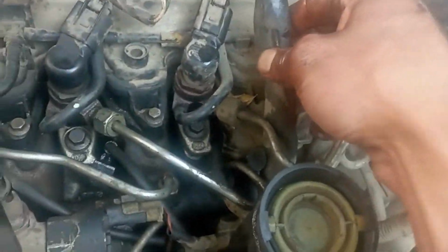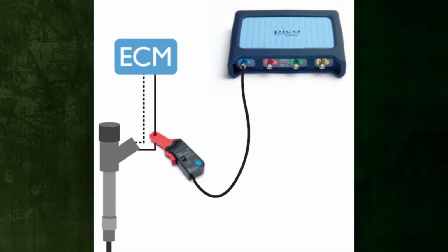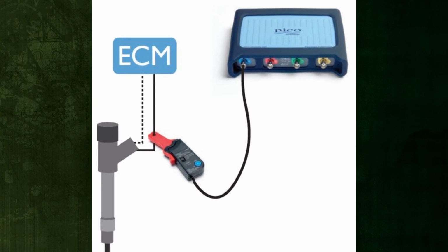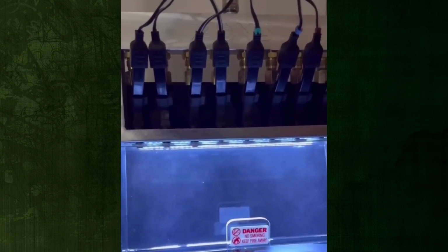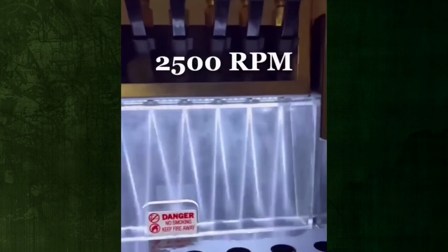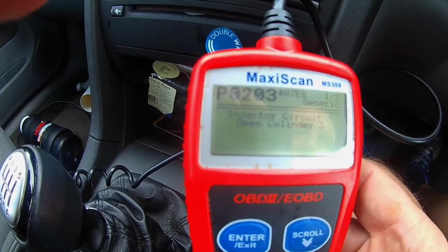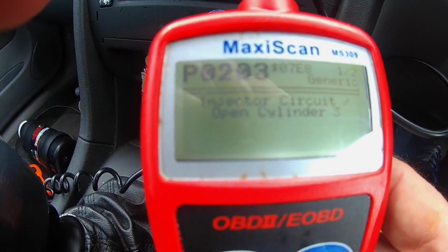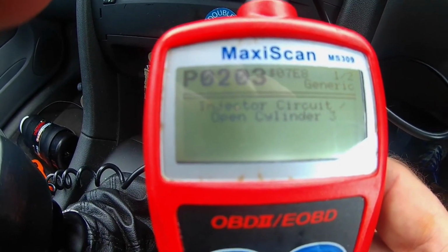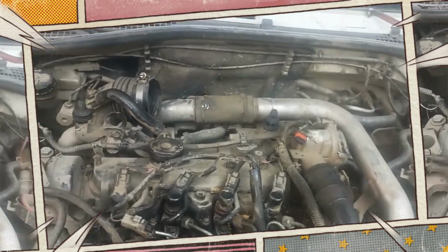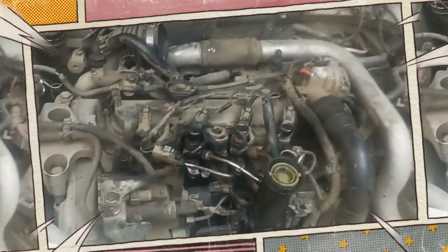To fully comprehend this principle, one must first comprehend the fundamentals of fuel injection operation. The ECM or PCM of a car powers individual solenoids, which operate each fuel injector in an engine. The ECM continuously checks each individual fuel injector circuit for measured anomalies in resistance and voltage. Diagnostic fault code P0203 indicates that during a commanded injection event, the engine's number 3 fuel injector circuit is not providing the expected electrical feedback to the vehicle's ECM or PCM.